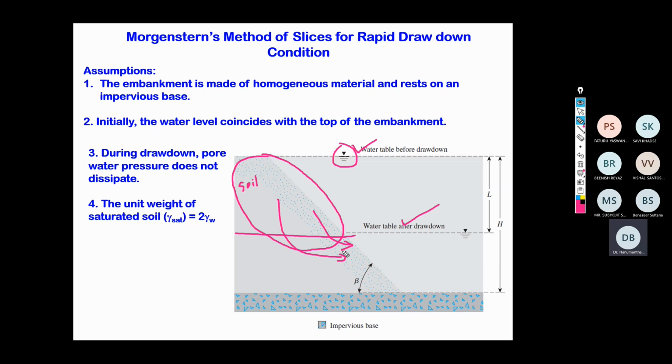Here we can recall the fundamentals of permeability and the fundamentals of consolidation theory. Permeability is dependent upon the soil type. Usually for canals we try to use somewhat impervious soils as embankment material.